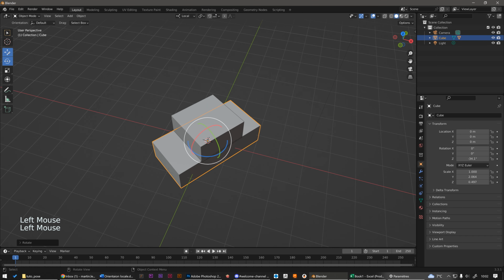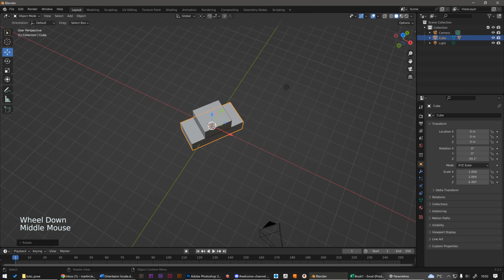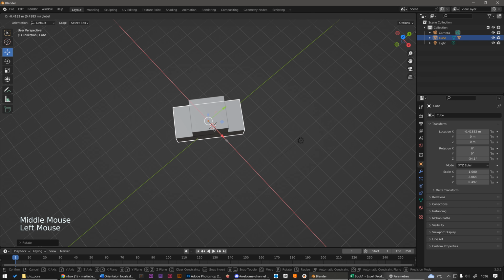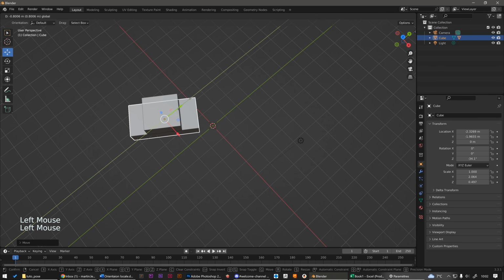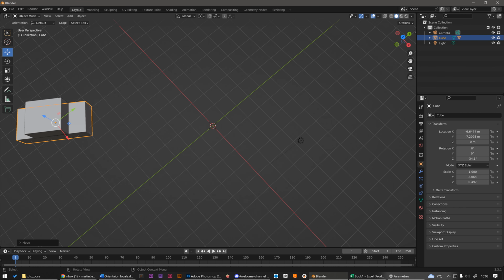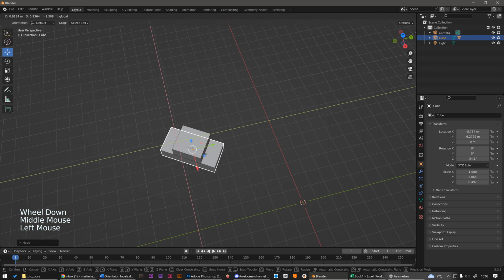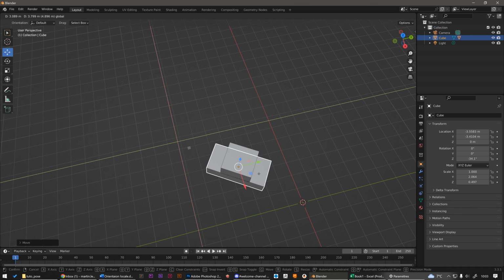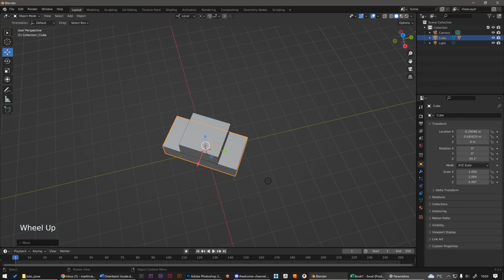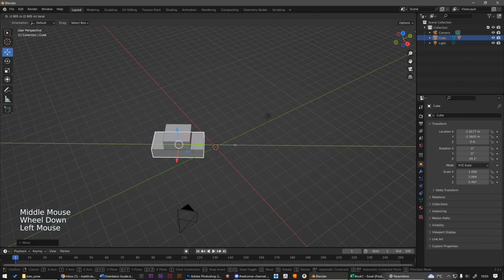And now how to make it move straight ahead in this new direction. In global orientation, I have no axis aligned with the car, so I have to use 2 axes at the same time to do zigzags as if I were tacking on a sailboat. I can also use the XY plane, but it's not at all precise. The car could slide a bit like it's rolling on ice, because I don't have anything to maintain the car in the direction of the movement. To solve that, let's switch to local orientation, and there, one of the 3 axes, so here the Y-axis, is aligned with the car, and therefore I can make my car go straight ahead.